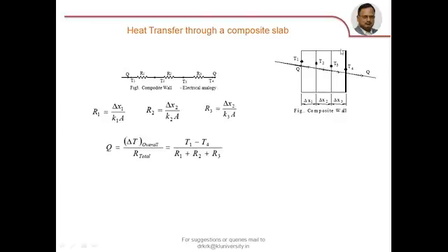This problem can best be represented in the form of electrical resistances like this. While heat is flowing through this, these three materials offer resistance for heat transfer one after the other. They do not offer resistance simultaneously.